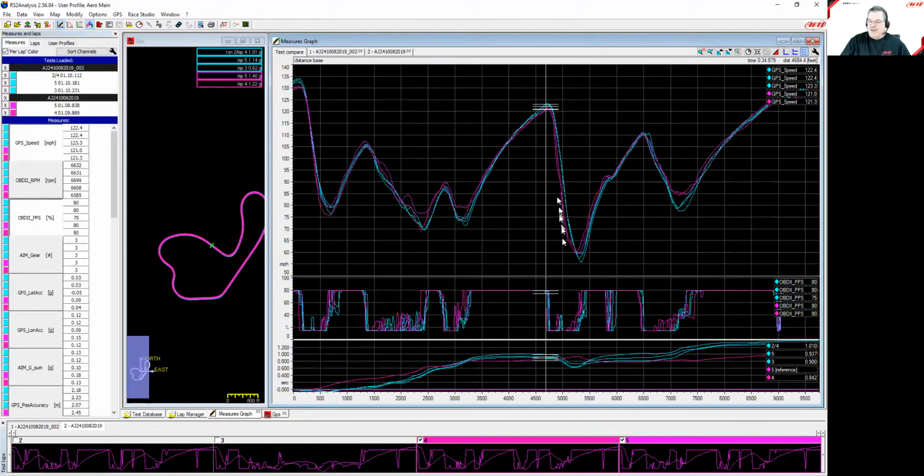This one here, this is an oddity, and I think it's just because there was a track change or something, because you have more grip, you have more downforce, should have more braking, but you're consistently off the brakes sooner. So my guess is there was some gravel, or some track change, or your brake pads are getting something, right? Because you're still able to roll through the middle, but you actually gave up a little bit on braking. So it may just be that's an area that I, as a driver, could have optimized.